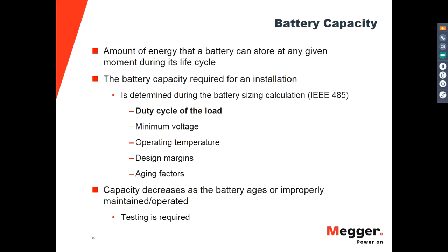This will also define the size of the battery, along with other factors such as the operating temperature, the design margins, and of course, aging factors. All of these define the capacity of the battery that is going to be installed for a facility. And as this battery ages, the capacity decreases, and this is where testing is required.